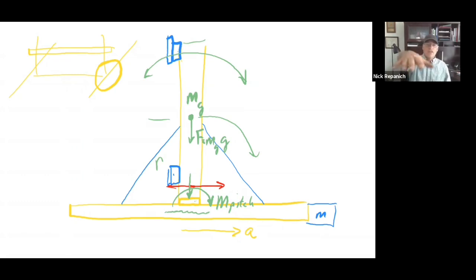It's like a robot arm moving around: its worst inertia is when it's fully extended. Sometimes you would say, I don't ever want to do this move back and forth. What I'll do is move in, lower the inertia, then move, and then go back out. And it creates a lot less torque on this axis right here.